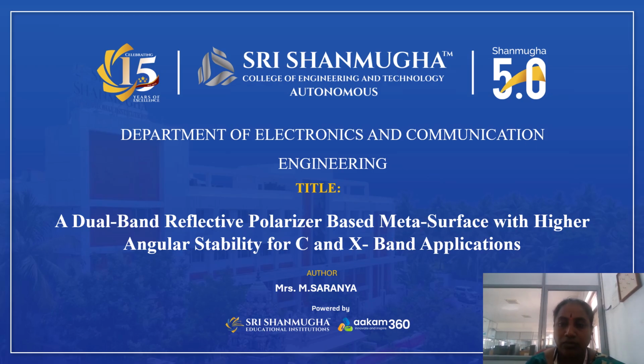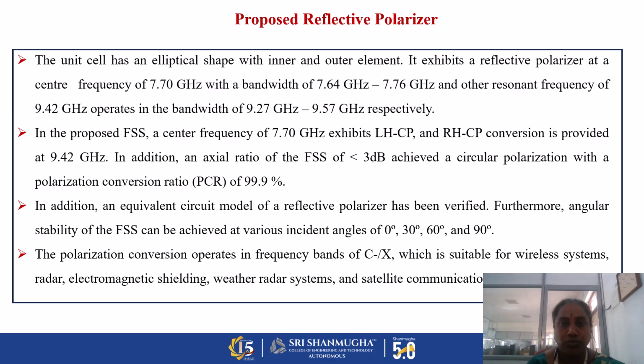So first, moving to the reflective polarizer, we are converting the linear polarization to circular polarization by using some FSS elements, that is the unit cell. In this related work, I considered an elliptical shape FSS. Here we designed the elliptical FSS. The frequency bands I chose are C band and X band applications.